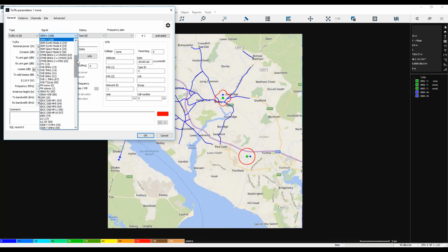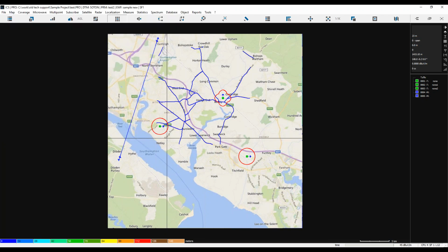when you're then coming to look at an interference situation and the C over I, what values is it going to use if you're co-channel, adjacent channel, etc., equally with different types of services, then it will work out how much protection you would get. So 20, 30 dBs, whatever it may be for that frequency offset that you've got.